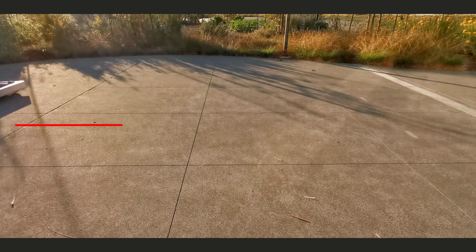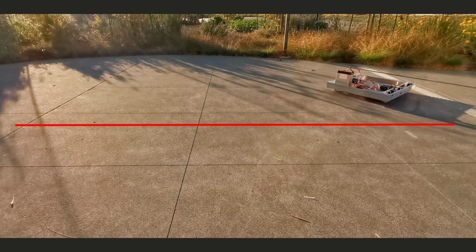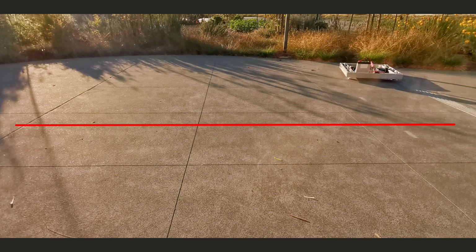In the demonstration, although the left and right motors had the same output, the robot slightly turned left. This is because we were operating the motors too violently and the wheels were slipping on the ground. Because the robot is not perfectly symmetrical, the slipping caused the robot to turn. This is not a worry since the wheels will not slip once we tune it correctly. And despite this turning, we can still learn that large KP values caused oscillations.